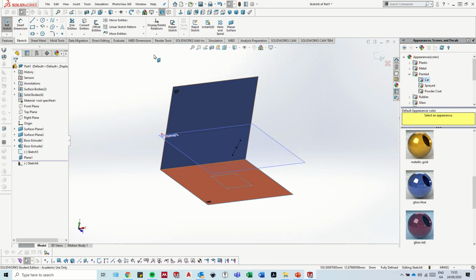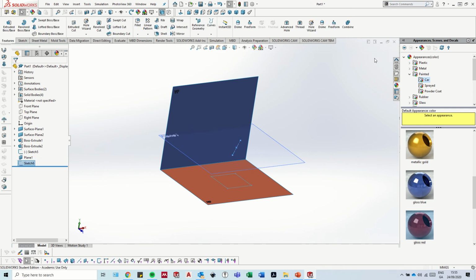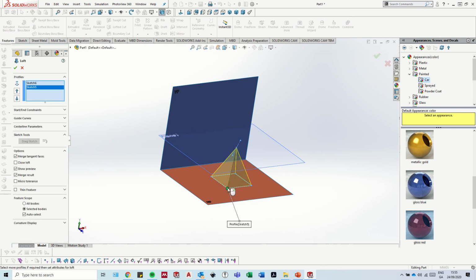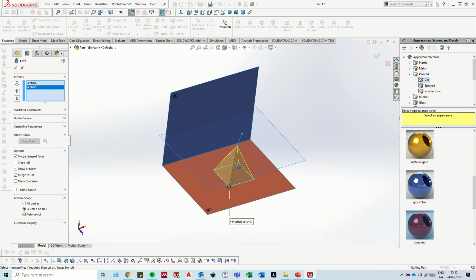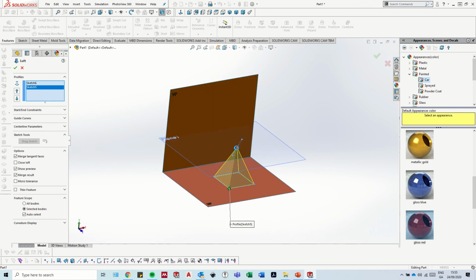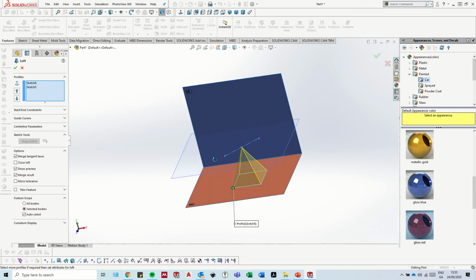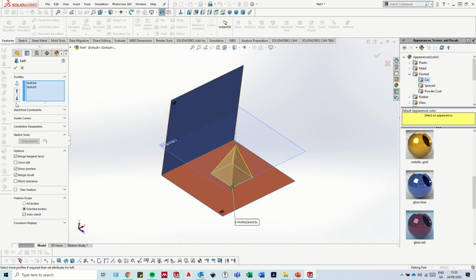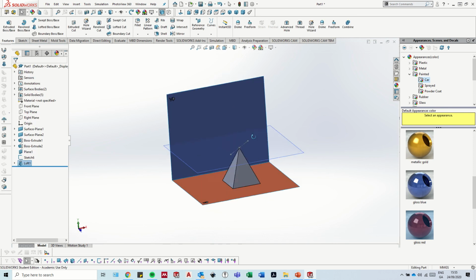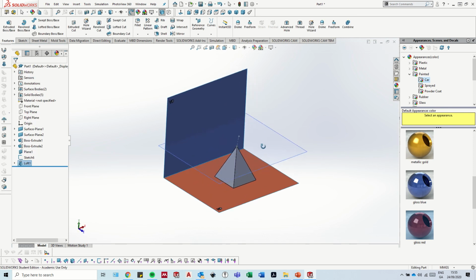So now what I'll do is loft it up to it. So I'll exit my sketch again. Features, loft, click my bottom corner here, and it already has that corner clicked, so that's perfect. You can unclick it if you want, like so. And when it's like that, all you have to do is click the tick. There you go. Now, a few problems we have straight away.